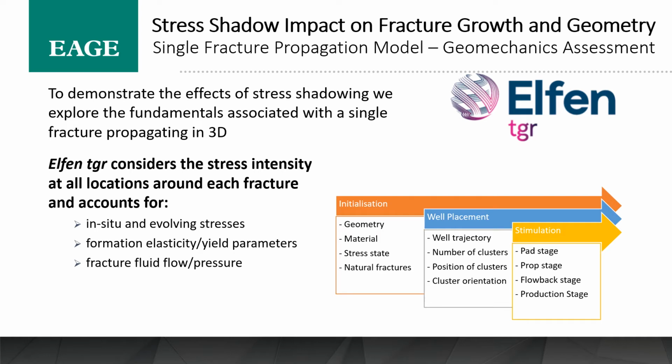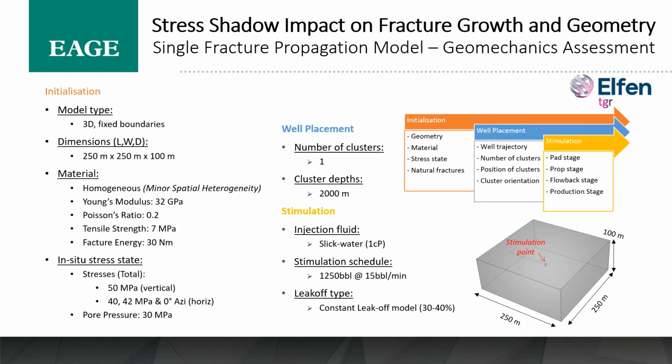So the modelling work that's been conducted for this presentation has been done using the Elfen software. This is Rockfield's Elfen software, and it considers everything of the geomechanics of the situation. So the in situ stresses, the evolving stress state within the formation, the evolving fracture growth and how that influences the stresses and then influences other fractures. So there's elasticity, yield parameters within the rock, and we also represent the fracture fluid flow within the induced fracture. It's very, very simple to set up these models, and they run very efficiently.